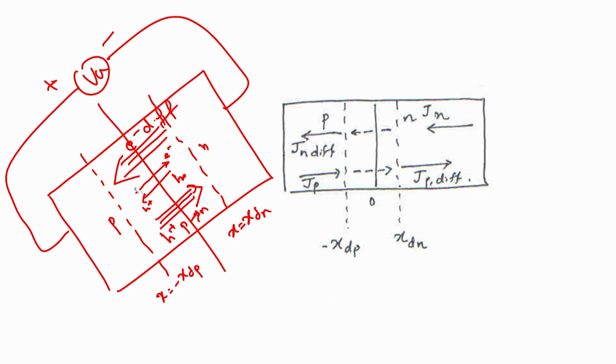Okay. So, for all practical purposes, the diffusion component is the current component, and since these holes are being injected, all this region is depleted. So, if you look at this boundary of the PN junction, at x equal to xdn, if you just look at this interface here, what is happening here? It initially has a very small hole population. At VA equal to 0, the hole population here is very small, right. It is Ni square by Nd.